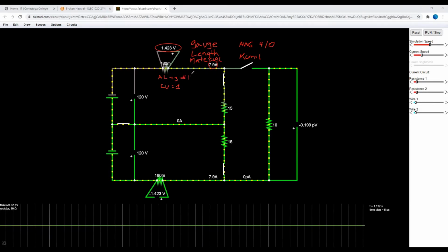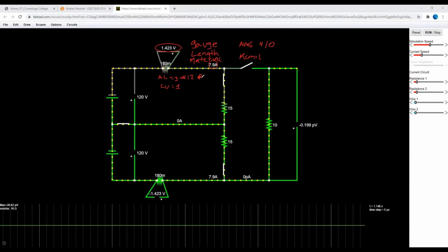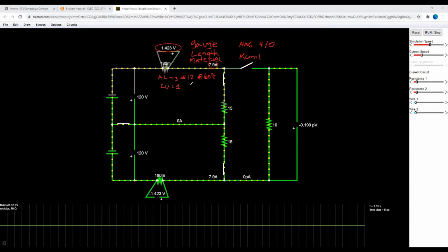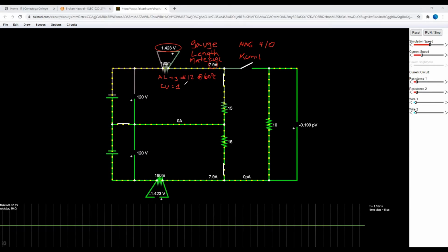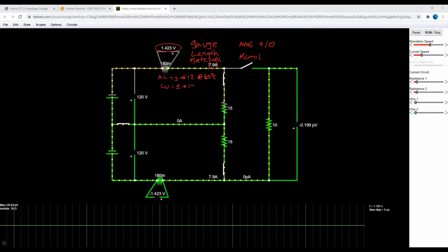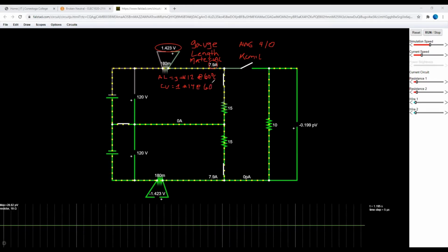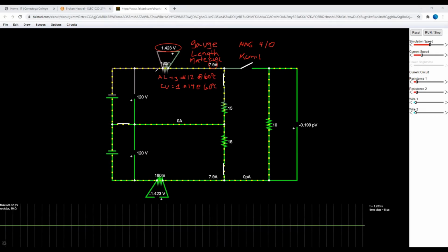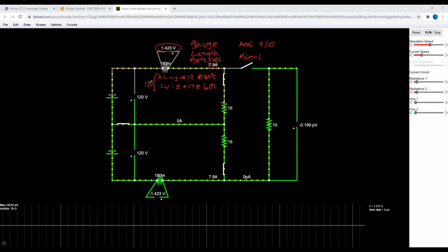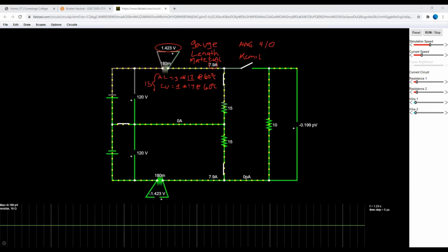That's going to be a number 12, at 60, with an insulation rating of 60 Celsius. While for copper, the minimum size conductor that we can use as per those tables is going to be a number 14 at 60 Celsius. And the rating for both conductors is going to be only 15 amps, despite the fact that aluminum is thicker because it's a number 12 than copper.